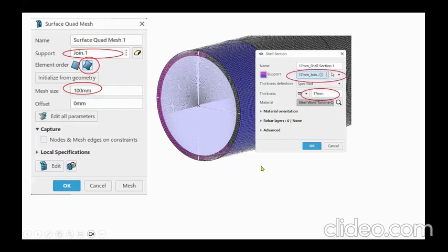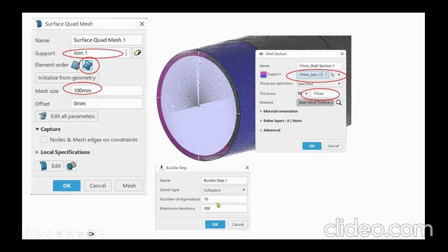And now if you run it, you may get a message about the default number of maximum iterations, which is 30. I believe that there's not enough iteration available. So what I did, I suggest you make this 200, and it worked fine.